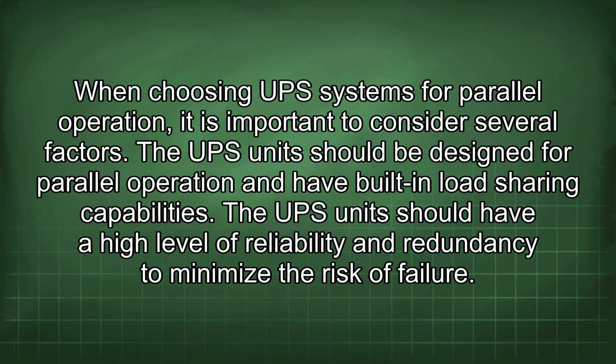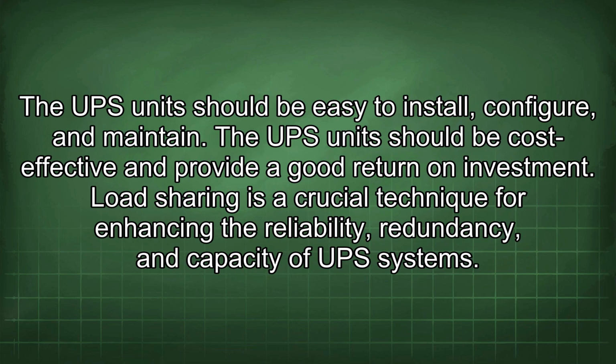When choosing UPS systems for parallel operation, it is important to consider several factors. The UPS unit should be designed for parallel operation and have built-in load sharing capabilities. The UPS unit should have a high level of reliability and redundancy to minimize the risk of failure. The UPS unit should be easy to install, configure, and maintain. The UPS unit should be cost-effective and provide a good return on investment.